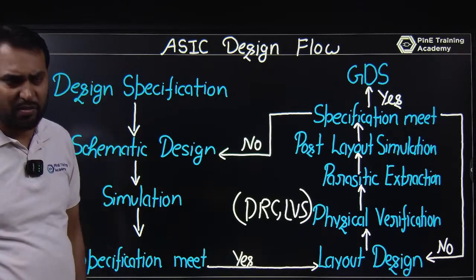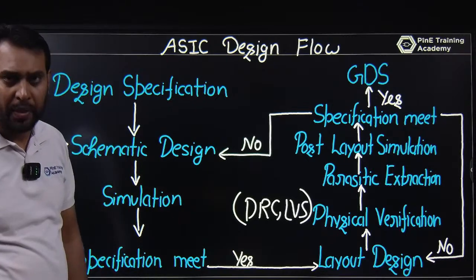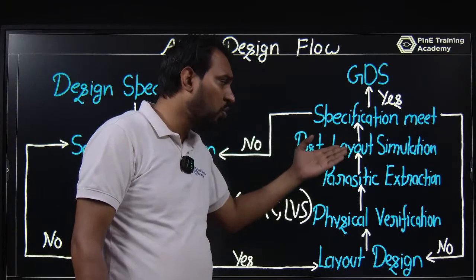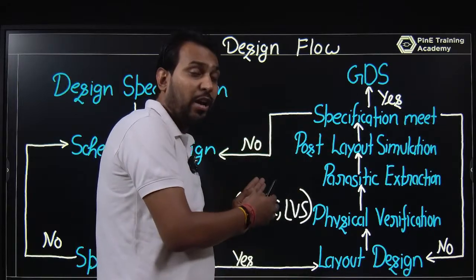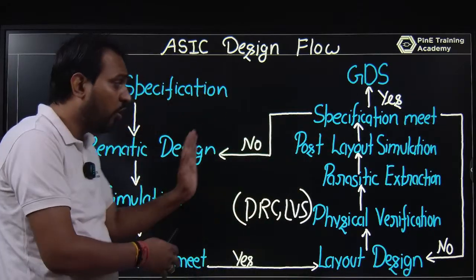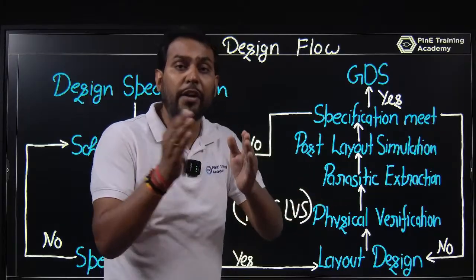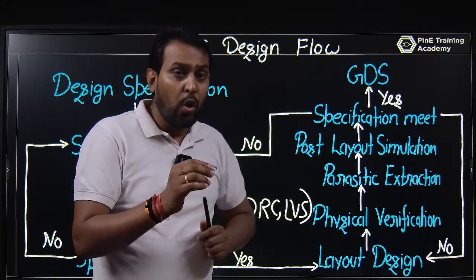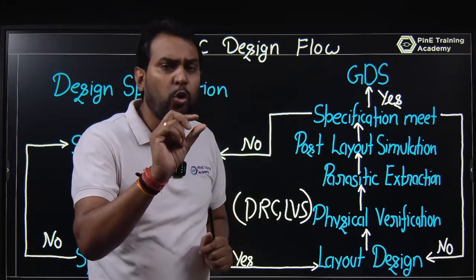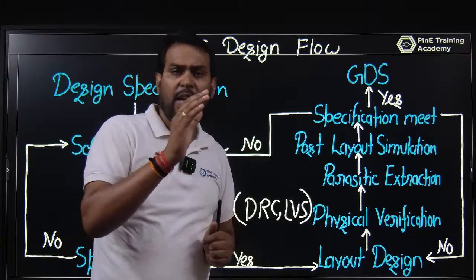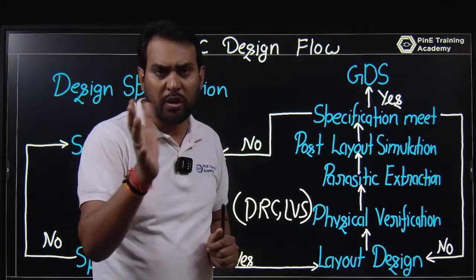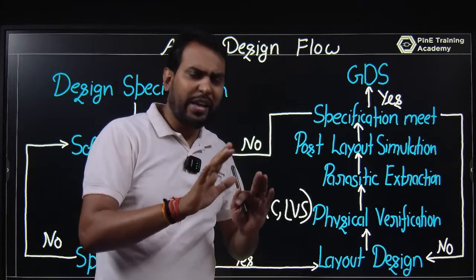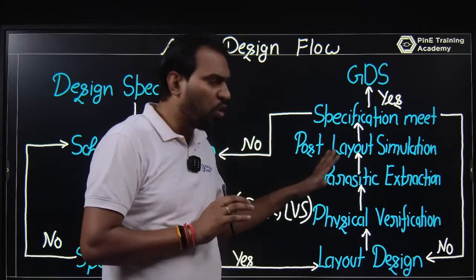I'm generally saying that the value is 120 picosecond. After the post layout, after the RC extraction, once you go for the post layout with the same values as given in the simulation, you have a difference. It may be 120 to 125. If there are 5 to 10% changes, meaning 120 to 132 picosecond, we can think that is okay.